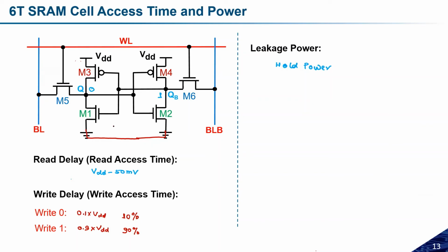We have to simply connect a voltage source in between, with 0 volt, and then check what current is flowing. There is no potential difference, no voltage drop across this source because the voltage source is 0 volt. And then I have to calculate the current.